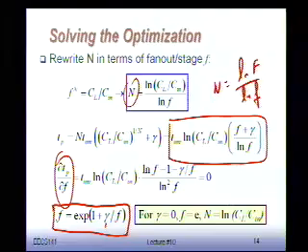And e is 2.718, you know, the standard number. So the optimal number, if you wouldn't have the diffusion thing, basically what it says is we should size up every inverter with respect to the next one by the factor e, 2.7. You make every stage 2.7 times larger than the previous one, and you'll get the optimum solution.